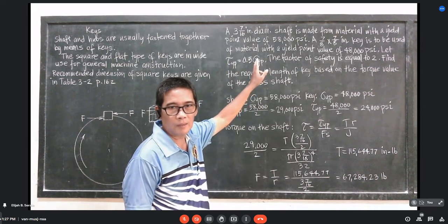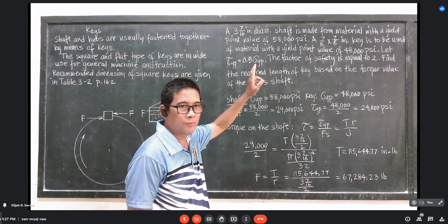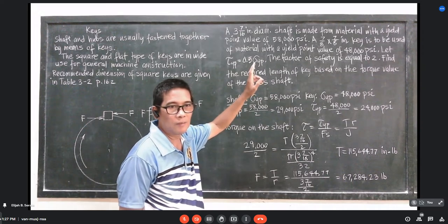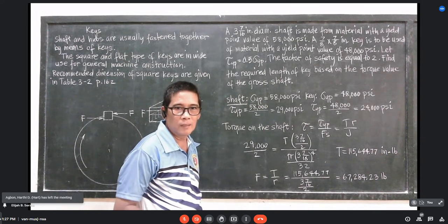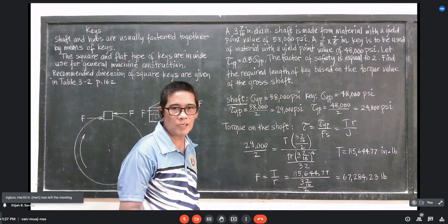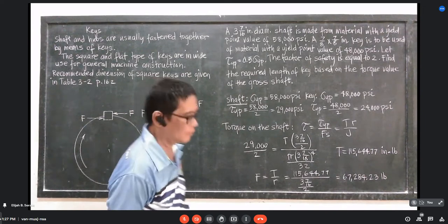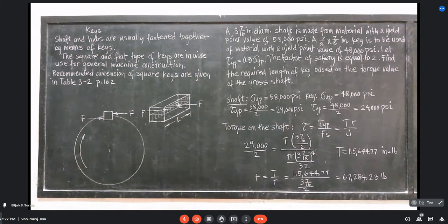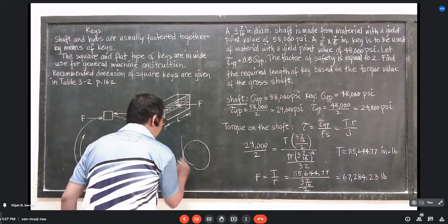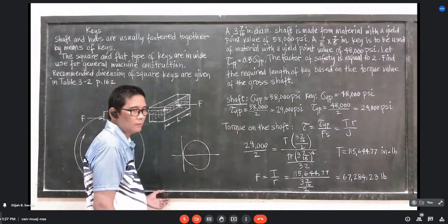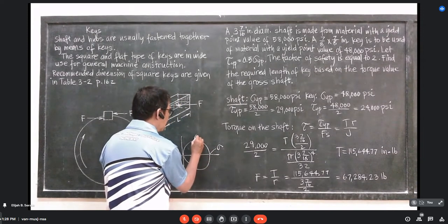We have discussed that, no? It is based on the Mohr circle, where for a simple tension, the value of the tensile stress, when compared to the drawn Mohr circle, gives a maximum shear stress of only 1/2, because in a simple tension, this is your Mohr circle, this is your tensile, and this is your shearing.